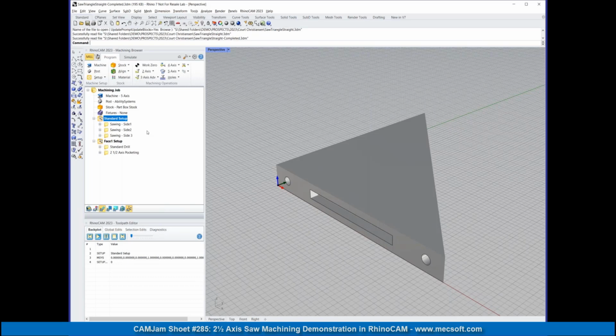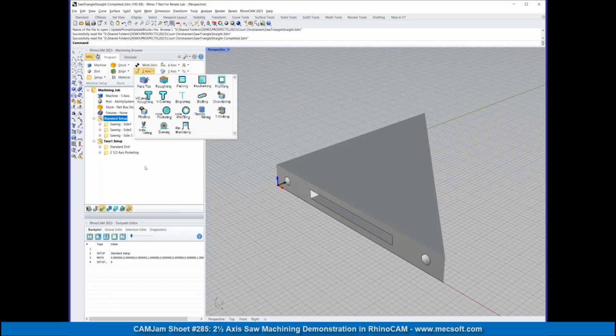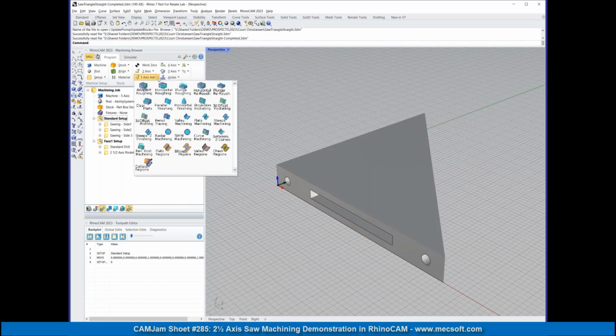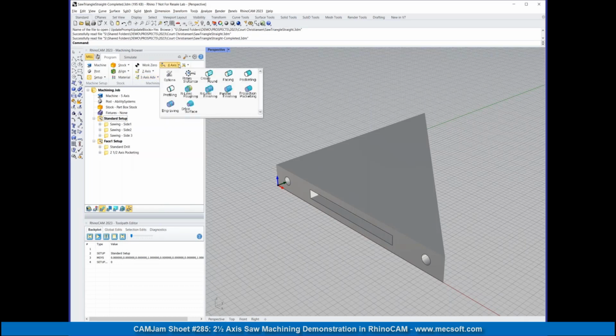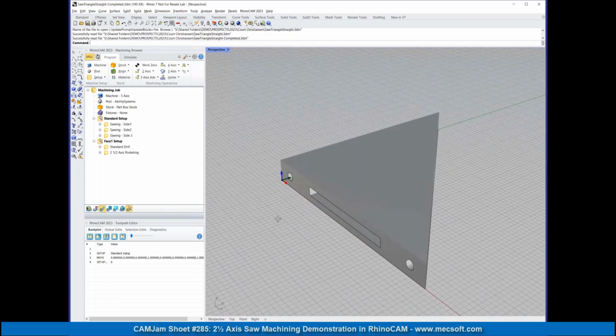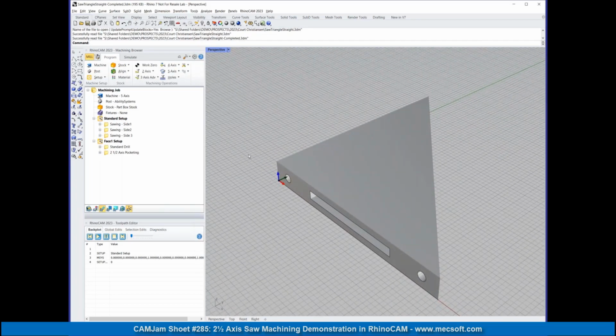Okay, all right. What you're seeing is the full 5-axis configuration that I have loaded here. In our program ribbon bar, you're going to see the 2-axis, all our tool axis methods, all our 3-axis advanced methods, 4-axis, which includes both wrap and true 4-axis, and then 5-axis methods and 5-axis continuous methods as well. When programming aggregate heads, we treat that as a 5-axis indexed operation.